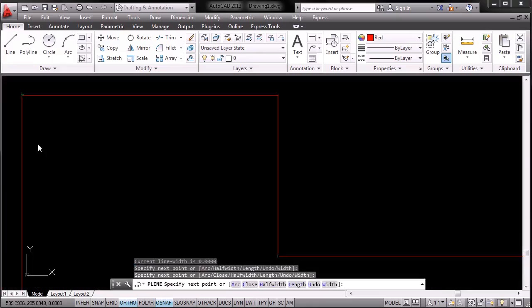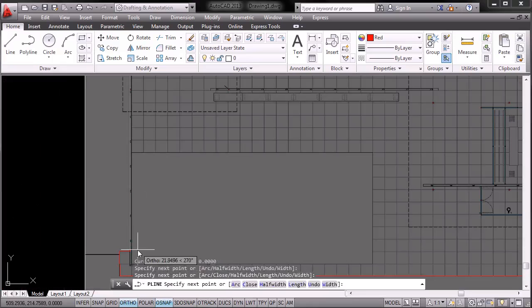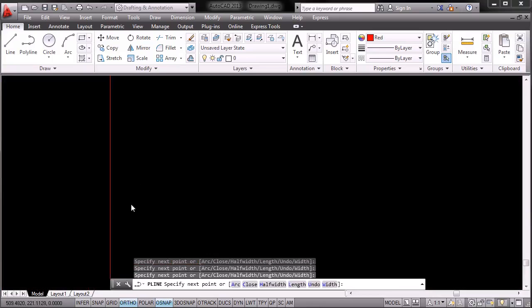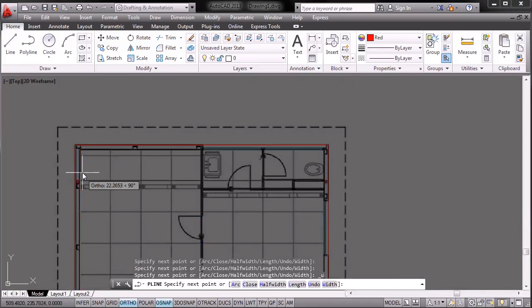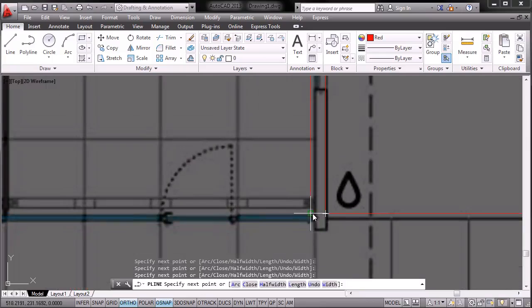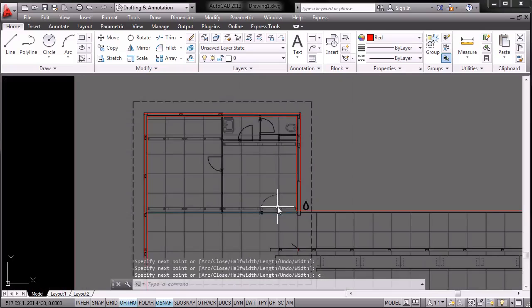If you see I'm going over again this line we already drew, it is because for the modeling process we need this wall to be an independent element from the contour of the building. As you see, by having the Auto tool on, it's pretty easy to draw these straight lines. So, click, click, click, and again remember to type close or just the letter C, enter, to have a closed element.